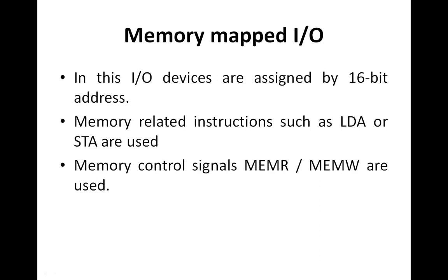But when it is the memory mapped input output technique, we will be using a 16-bit address. We will be using all the instructions which are related with the memory, that is LDA or STA, and instead of input output read and input output write control signals, we will be using memory read and memory write control signals.